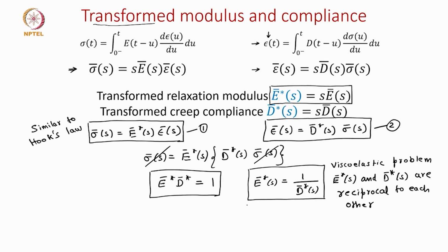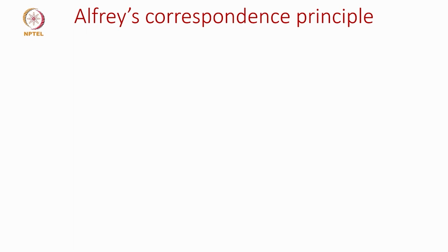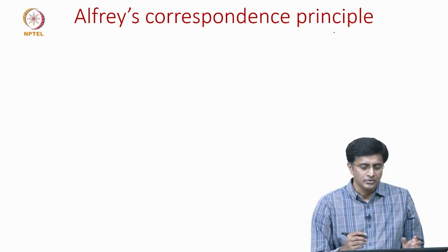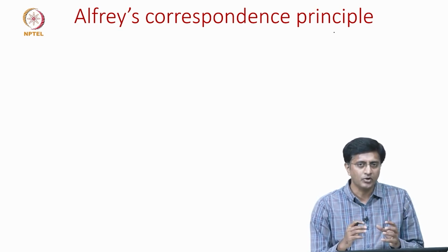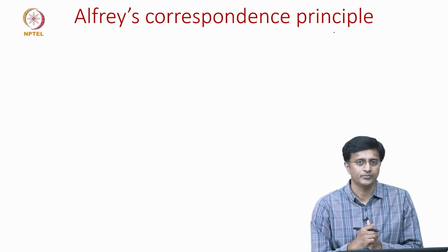So, this is another very important conclusion we came to, saying that we are now able to relate between the modulus and the compliance, but this relation we are able to show in the Laplace domain. So, using these observations, now we will come to the most important concept of this video, which is the Alfrey's correspondence principle. So, this principle says a step by step procedure about how to solve a viscoelastic problem.